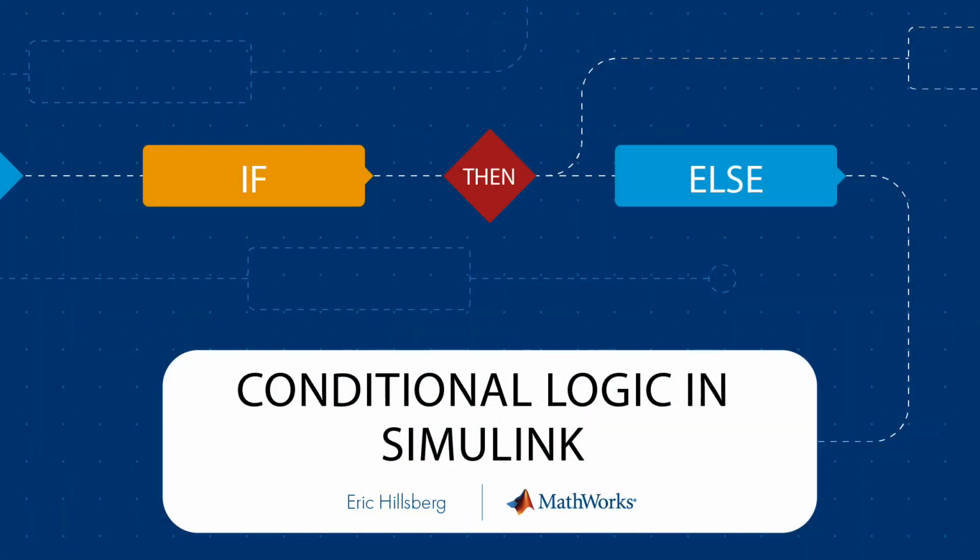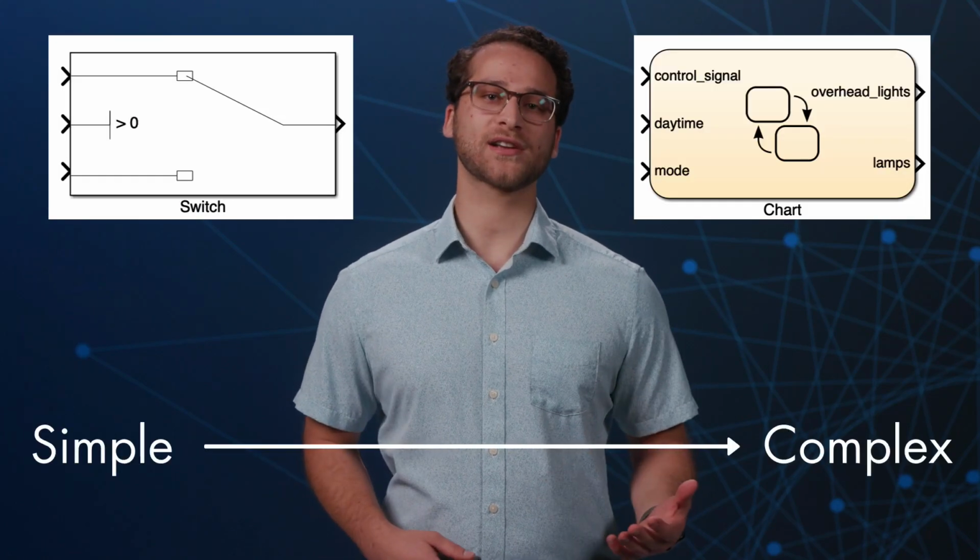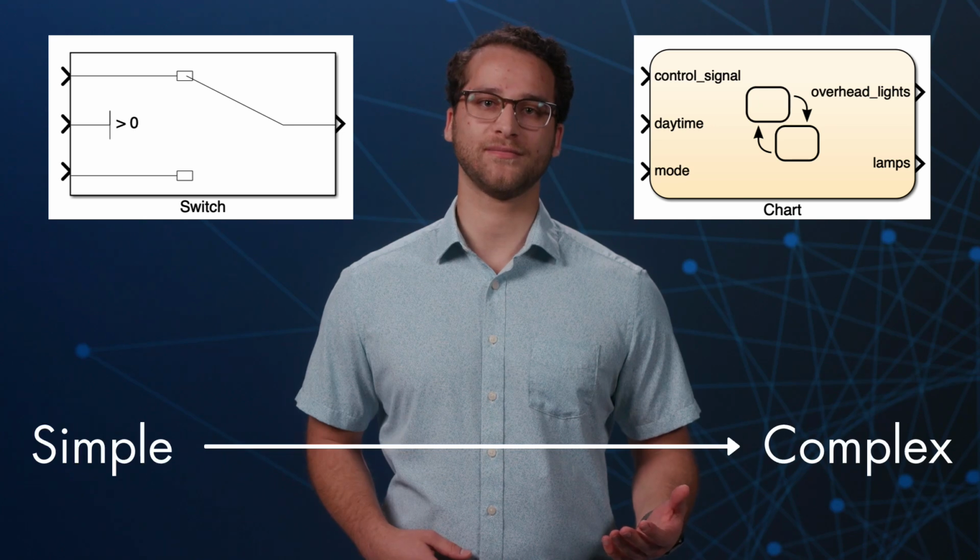Hi, my name is Eric, and today we will be talking about conditional logic in Simulink, where you can modify output signals based on inputs. Conditional logic is especially useful in modeling nonlinearities of systems, but it can vary in complexity, from a simple switch block on one end of the spectrum to complex logic in a Stateflow chart on the other.